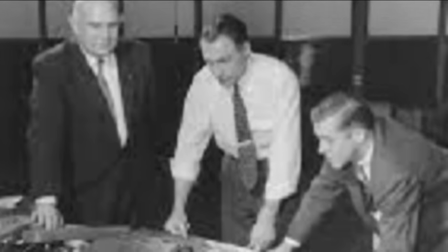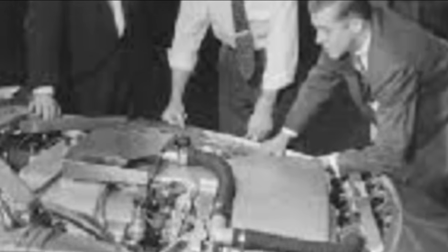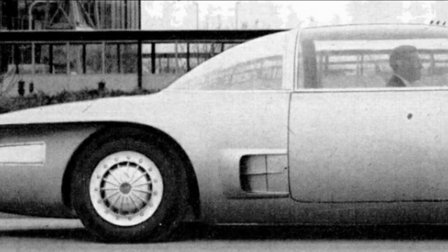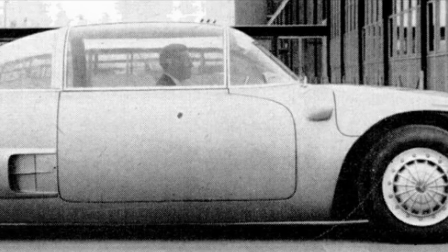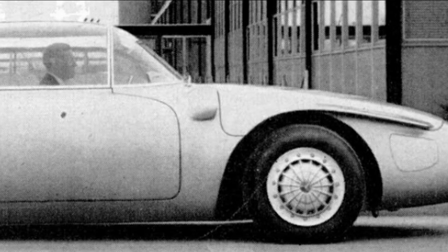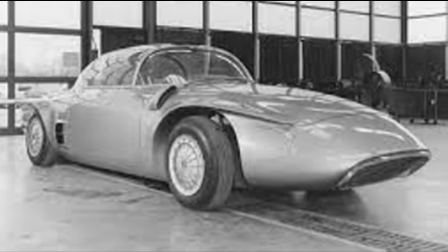In 1956, General Motors experimented with the GM XP-500 Firebird passenger car, equipped with a twin-piston gas generator producing 250 horsepower, a 5-stage axial flow turbine, and a 7:1 reduction gearbox. This car's power plant could run on virtually any fuel, including kerosene, fuel oil, and vegetable oil. It was reported to be virtually vibration-free, with thermal efficiency ranging from 32 to 36%. However, problems with starting, lubrication, and engine control apparently proved insurmountable, and the experiment was abandoned after 3 years. The Firebird remained a prototype.